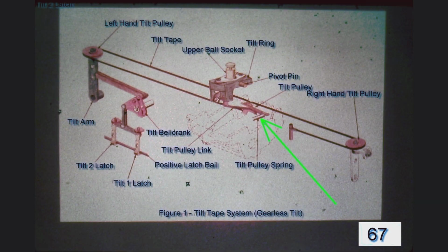Here is the catch. To rotate clockwise, the bell crank would have to lift the vertical link up into the tilt differential, and that lever is caught against the stop pads, which keep the tilt latches from moving upward. So the whole system is held up against those latch stop pads, and the bell crank goes nowhere until a latch is pulled down.